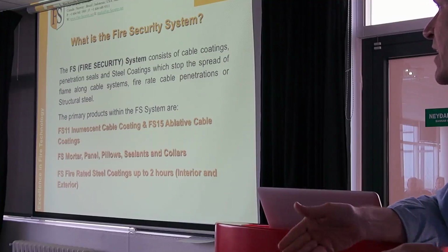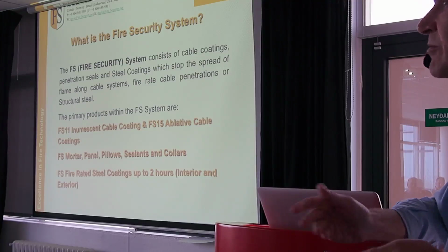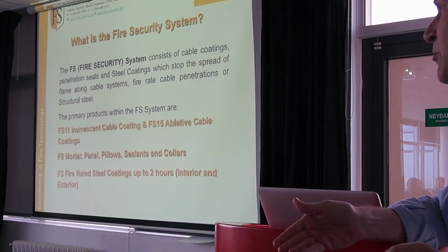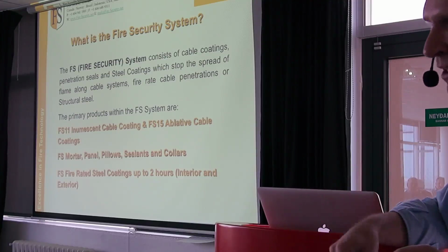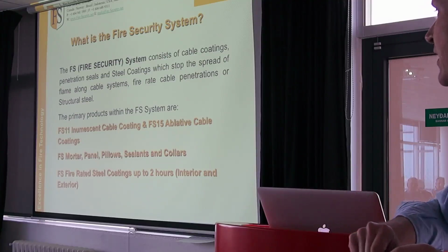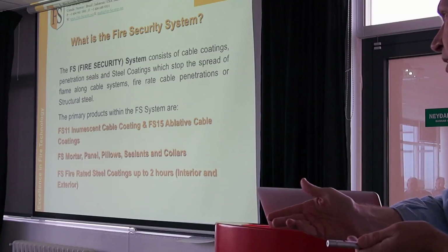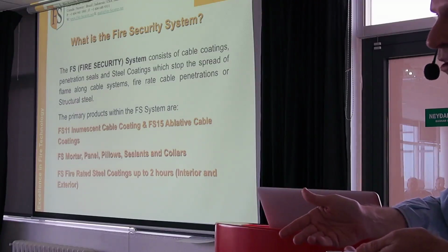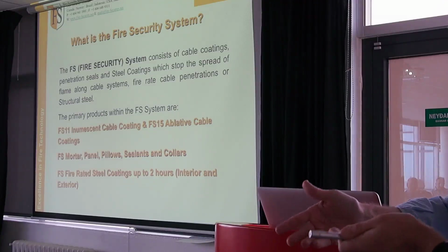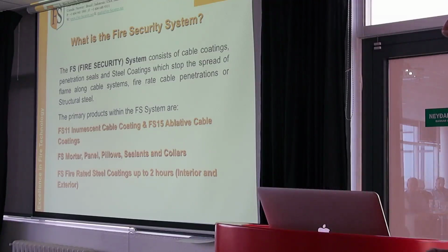But when we devised our system, we devised 5 products, because these 5 products are the 5 most used products. They're the most practical products. Our mortar is 6 hour fire rated. Our panels are 4 hour fire rated. You'll never see a 6 hour fire rating anywhere. We simply didn't turn the test off because we wanted to see how long it would last.